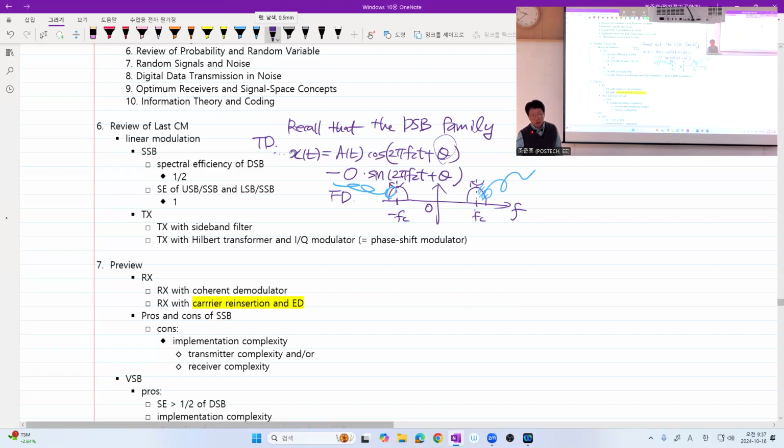The answer is, interestingly, yes, because if you consider a coherent demodulator, still you can recover the signal. You can also remove this part. In that case, if you can build a phase coherent demodulator for your reception or detection of the message signal, then still the message can be perfectly recovered under the assumption that there is no distortion, no noise, and so on. Got it?